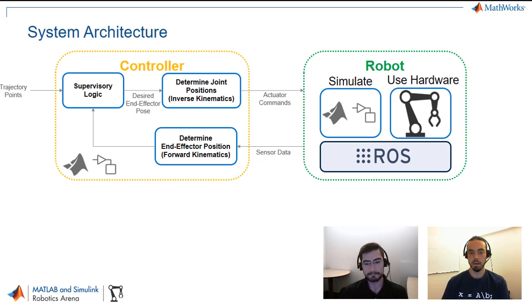Awesome. So for those that are less familiar with manipulator algorithms, just as a reminder, whenever we talk about manipulator algorithms or robot arms, there's this notion of forward and inverse kinematics. Forward kinematics is, given all the angles or the translational degrees of motion of your robot, like all the motor and actuator positions, the combination of those positions is going to lead to the gripper or the end effector of your arm being in a certain position.